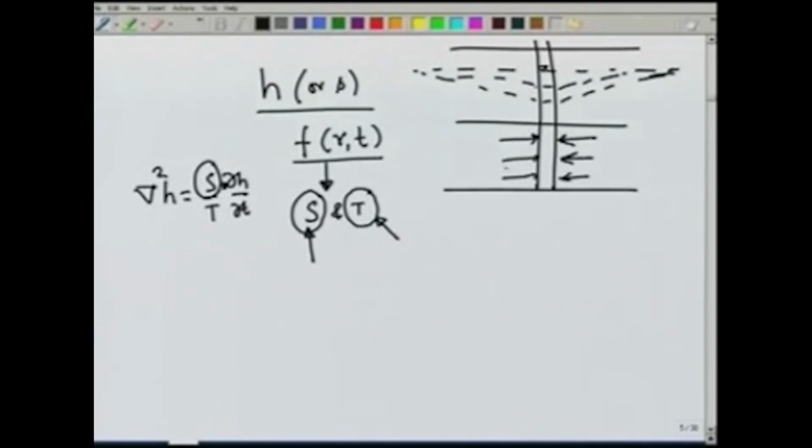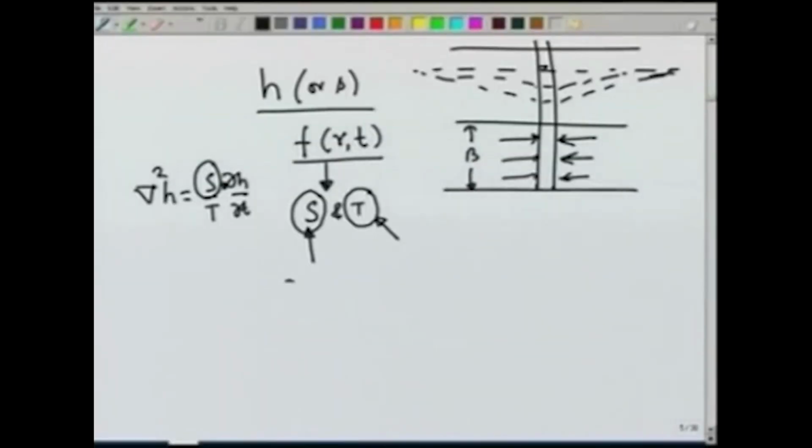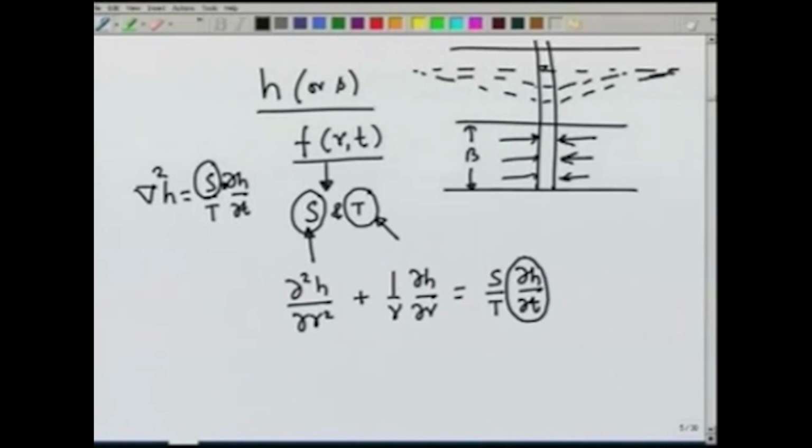So, we have a fully screened well, constant thickness of B. The only assumption which we have now relaxed is that instead of being steady state flow, the flow now is transient, and therefore, the drawdown and the H will both depend on time also, and therefore, the equation governing will include the transient term del H over del T. Now, partial of H with respect to T will not be 0 in this case, while in the steady state case we have taken it as 0.